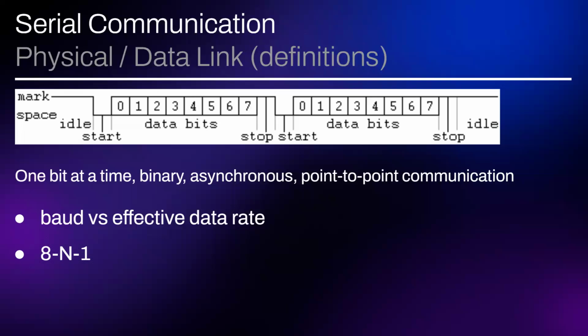The N is a little confusing. We'll get back to that in a second. And the 1 is how many stop bits. In the old days, they used to send 1 or 2, or I think there's even a 1.5 bit setting for stop bit. It's weird. A lot of serial stuff is weird because it's really old. Things didn't work as well back then. Now things are pretty well ironed out. But in any case, this is how many stop bits you have.